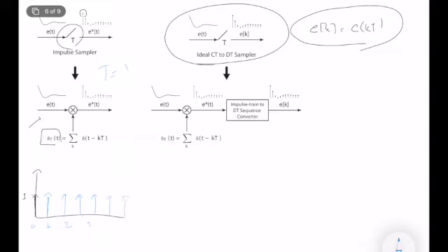Okay, so I multiply two signals. What is important here is that this operation, multiplication of two signals, we haven't covered throughout the class because it is inherently a nonlinear or time varying operation. Multiplication of a signal with a different signal is not a linear operation, or it is time dependent.